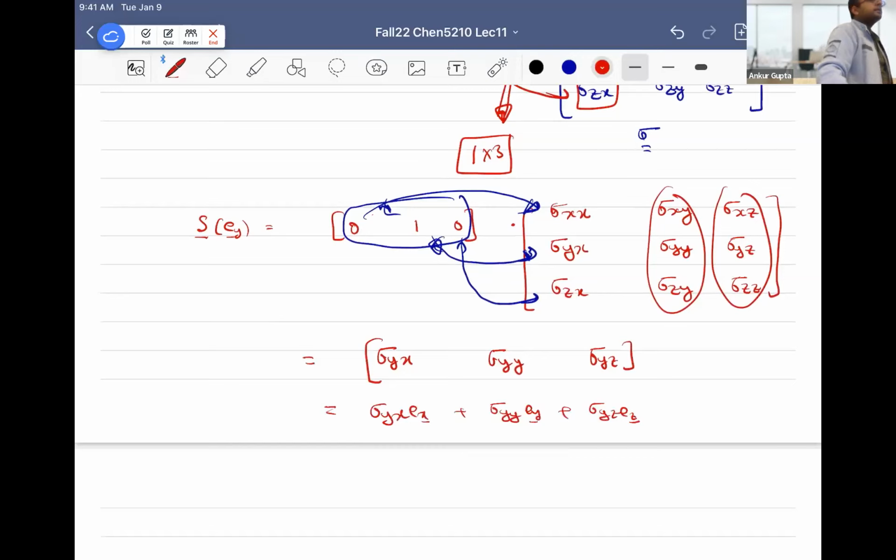All right, where do you think the complication will start to happen? So we get this answer, and this really makes sense. This is when the normal is no longer something as simple as EY. When the normal is curved, then your normal will be changing, and then you'll have all these combinations of the stress tensor coming through to get the force and final stress.